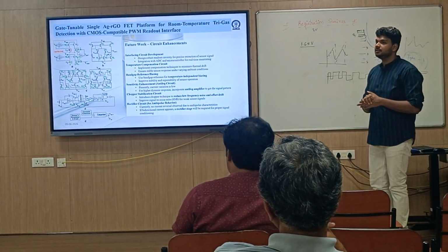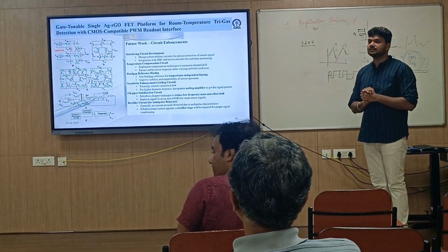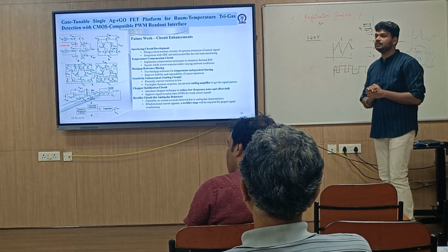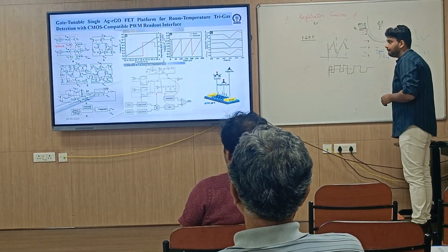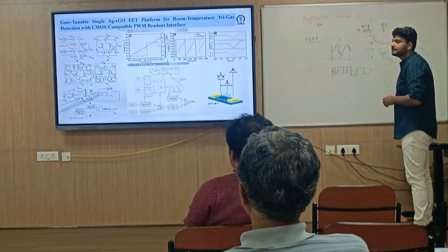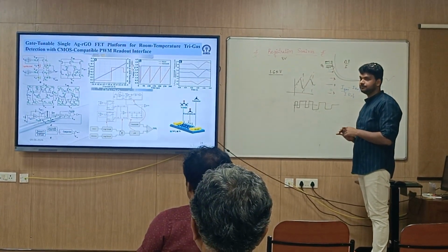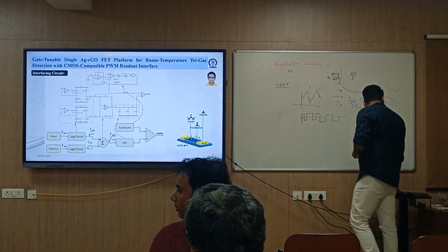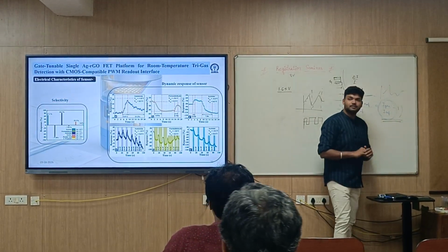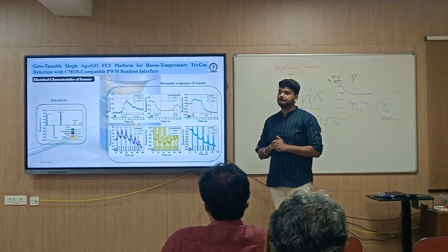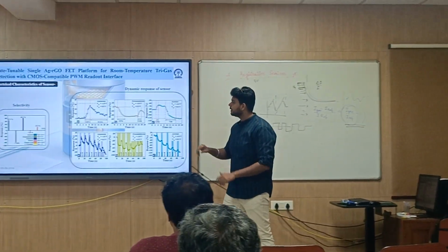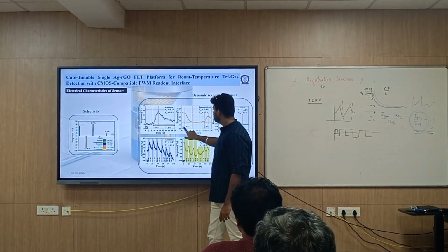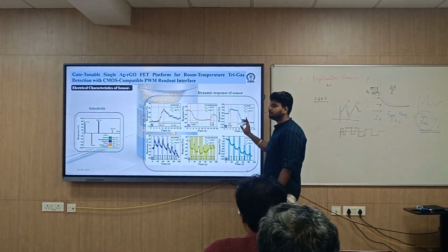For the first part, I have one observation: your ramp rate. There should be a relationship with your rise time and the recovery time. Have you considered your ramp rate? Because it is almost like a quasi-static process, you cannot do it very fast. You need some time to charge up, because it's a FET. Considering your millisecond time, how do you optimize that ramping? We have seen the response time is approximately 3 seconds for 5, and 2 seconds.